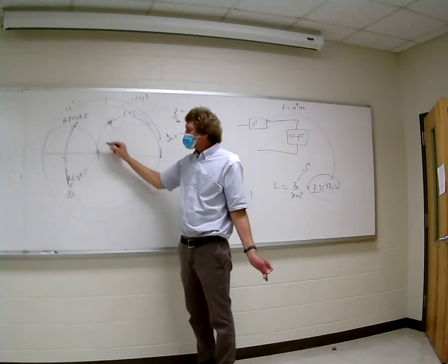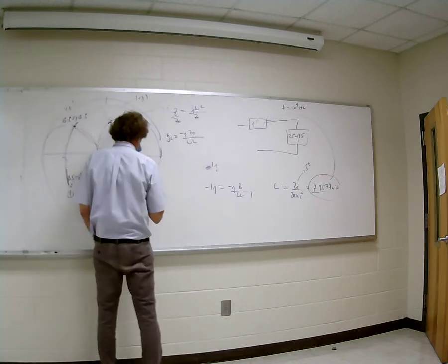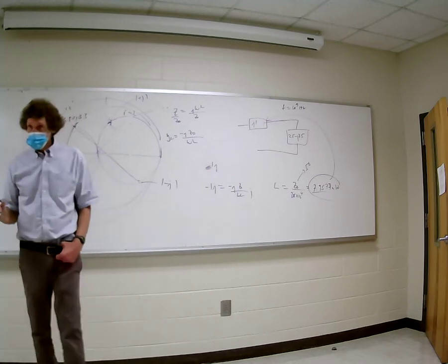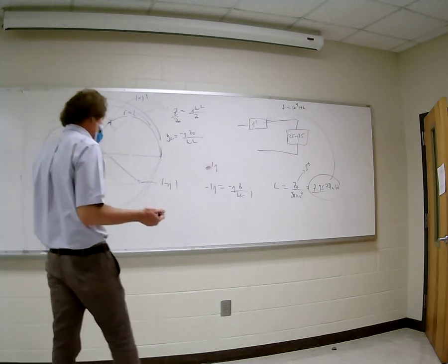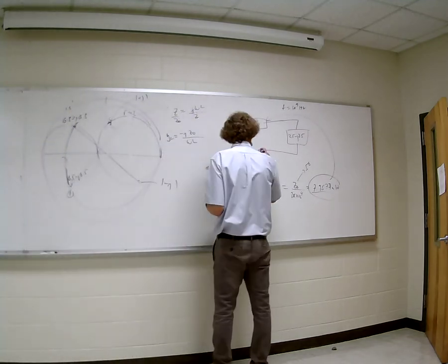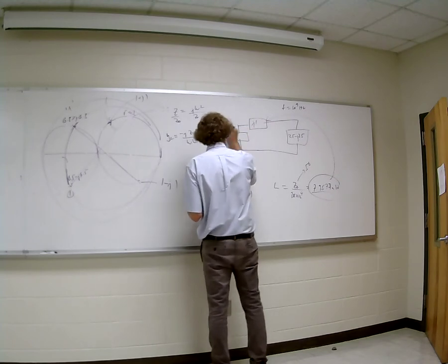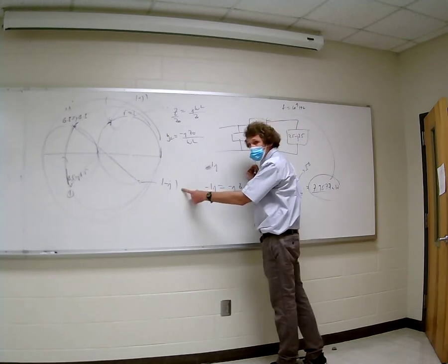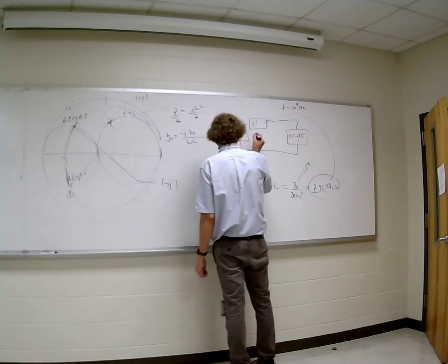Now that's the impedance domain, right? Now we go to the admittance domain, take 1 over that, and what do you get? 1 minus J. This is 1 minus J1, right? Right. Isn't it, guys? That's the admittance domain. Now we have to add something in parallel, an admittance in parallel to get rid of that. And what's the admittance going to be? If it's 1 minus J1, we have to add plus J1 to get rid of the negative minus. So we're just adding J1 right here.